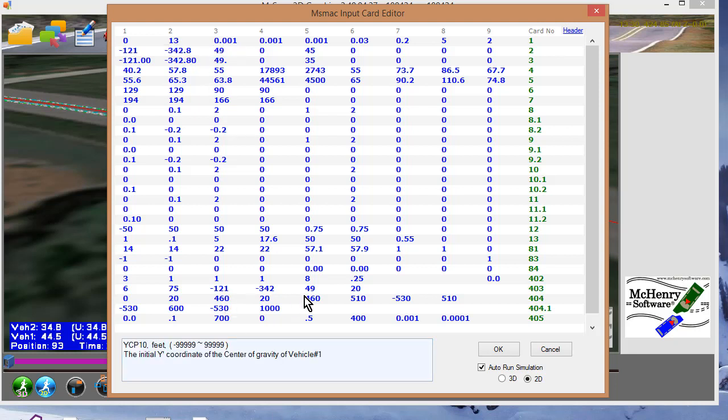So you put the X, Y, and heading angle. How I moved them is when I brought in that drawing of the ground, you just move the car to the point where you think it starts, and then we create a path to follow the path, and we'll talk about that. Next item is going to be how many feet between points, and I just put 20. You can put as many as you want. Generally 10 or 20 feet is good.